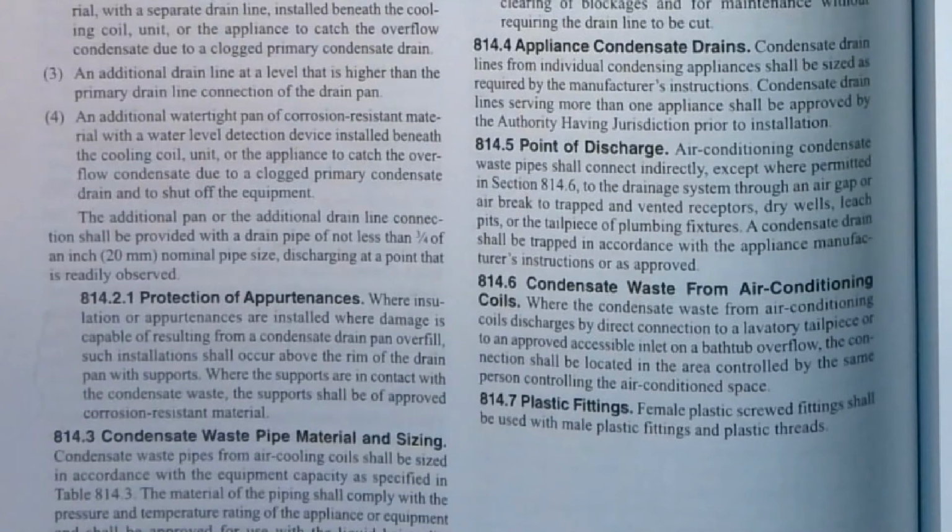However, as you tighten a female plastic screwed fitting onto copper, that plastic wants to expand, especially if it gets cold and warms up. And that stuff is pretty brittle and it will actually crack. So female plastic fittings go to male plastic fittings. They both have a certain amount of give to them and they're not as expansive as copper is.